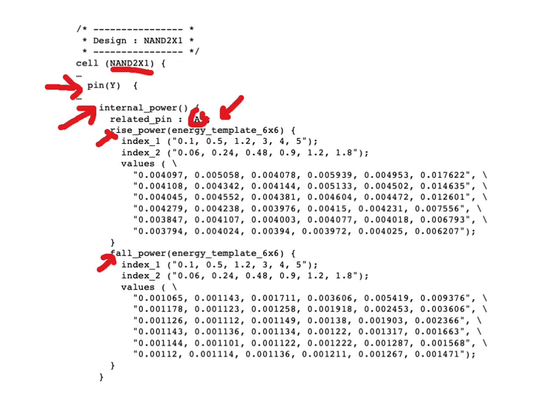And this section of the definitions only refer to rise transitions on input A that cause a transition at the output pin Y, or fall transitions at the input A which cause an output transition in output pin Y. For rise transitions or fall transitions at inputs that do not lead to an output transition, we will cover how a .liberty file can specify the power consumption there.